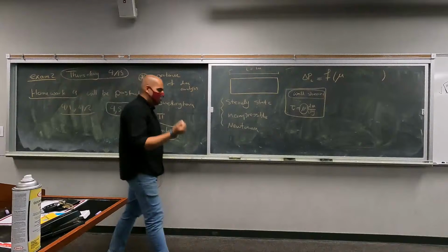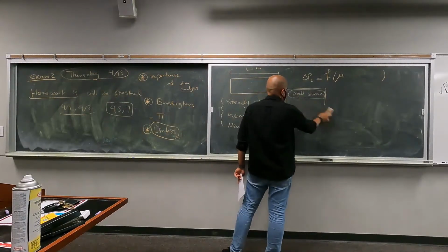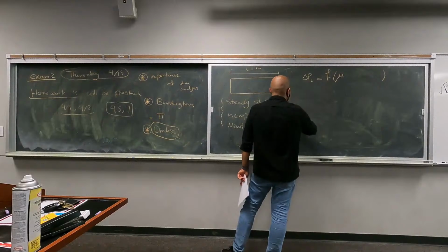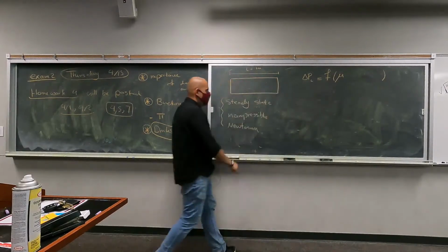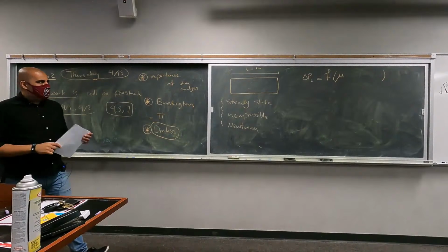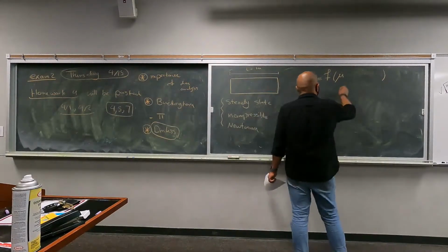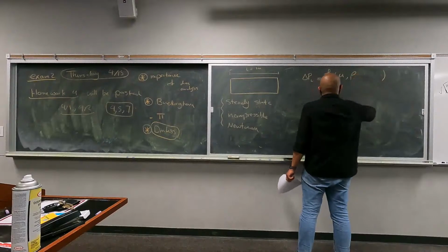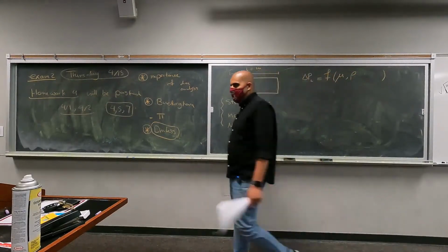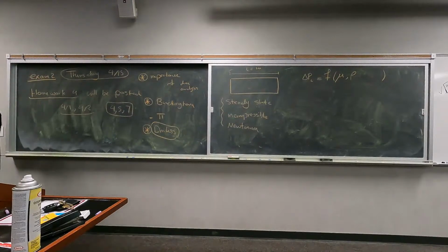Again, we said wall shear is going to be important when you include the effects of viscosity. It's a pipe flow inside the pipe. There's no way for us to neglect those effects. So pressure drop inside the pipe is a function of viscosity. Okay? And what else? Usually your fluid flow is always a function of density, right? Density appears in all of the governing equations. It's a very important factor.